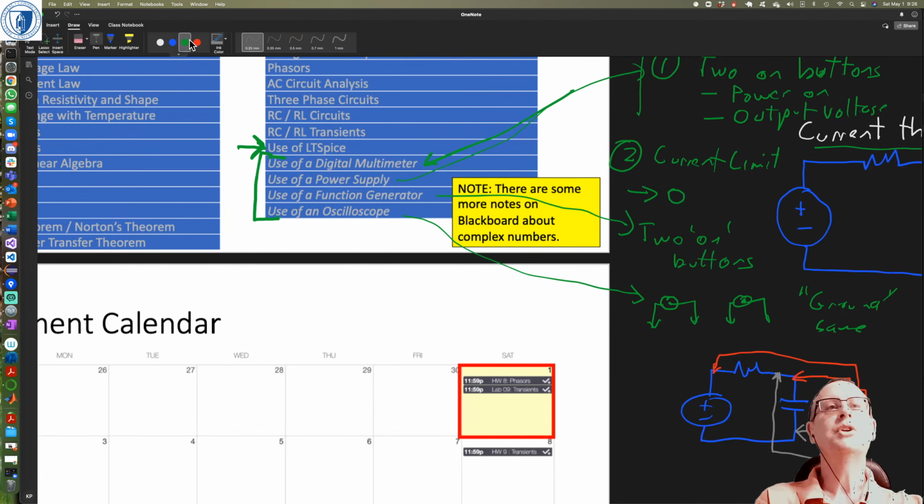Okay, the trouble is both of these grey leads are ground. So by putting that common ground lead on both sides of the capacitor, you make the voltage across the capacitor drop to zero, because both sides of the capacitor are grounded. Anyway, I just thought I should talk about some of those things.